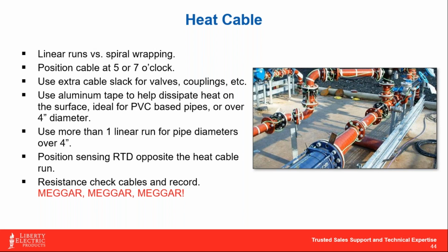So typically we recommend running that heat cable at, say, 5 or 7 o'clock. If we imagine the clock face, we want it on the bottom of the pipe so that as the heat is dissipating onto the pipe, we know it's affecting the part where we're worried most about it freezing or congealing. Okay, so